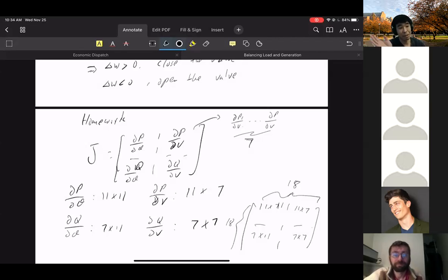When we look at line flow, if we do that, some lines would be carrying like 200 megawatts coming out of the slack bus, so that makes the line flow harder. So if you can switch over, just change the column, change how you read the data. Rerun the program. If it's already hard coded in, that's fine. So for a PV bus, should I treat the P column as the generation? Yeah, treat column B as the generation. Okay, and just basically ignore Q? Yeah, ignore Q.